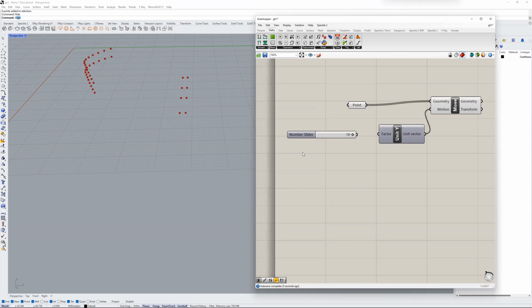But there's a quicker way of creating sliders, and you might want to write this down. You start with the minimum value and you type that in. So let's say we want a slider that goes from negative 10 meters to 10 meters. So we're going to type in negative 10, that's a number. Then we're going to use this less than sign, and that automatically turns it into a slider. And we're going to put in the default value, whatever value you want it to be by default. I'm just going to set 0.